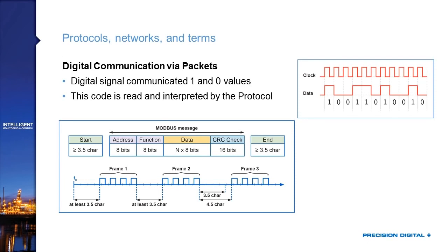So to give you some idea, you have what this data signal may look like over here, where it looks like some kind of odd square wave. And really what that is doing is that it's changing the waveform such that in this case, on every falling edge of a digital clock, it's taking a reading, and it's reading these high values as 1s, and it's reading these low values as 0s. And that's really the difference between having something like an analog signal and having a digital communication signal. An analog signal is going to be sweeping over time to all of these different values. A digital signal is a timed 1 or 0 that's being transmitted.